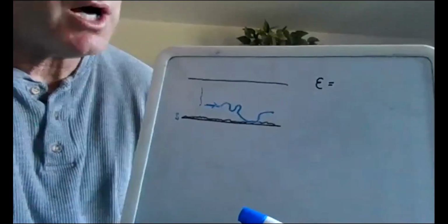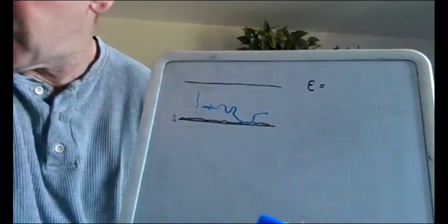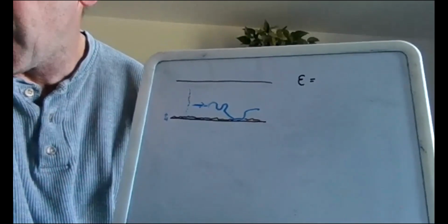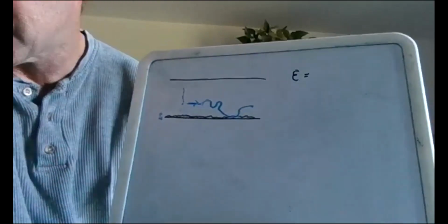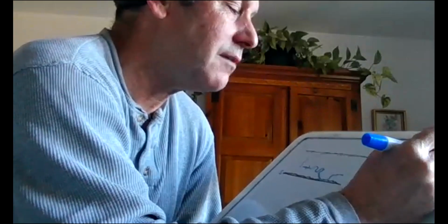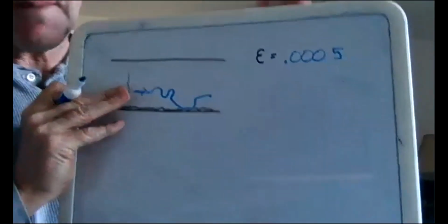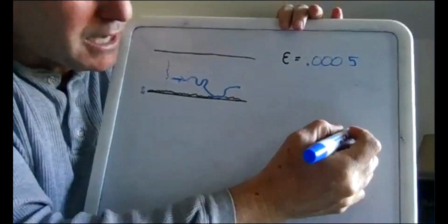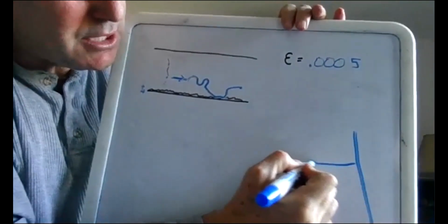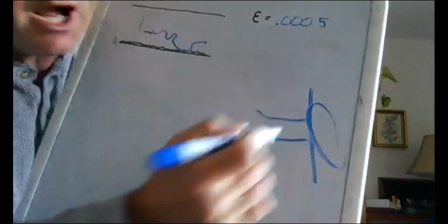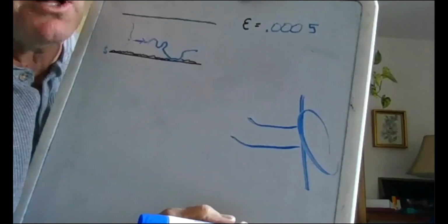All right, so for your Moody chart, table 8.1 in the book nicely has some common pipe roughnesses. We can always look them up for any particular pipe. We're going to do galvanized iron, and so 0.0005. All right, if you think back to the Moody chart, the column on the right side, which we use to get those curves, is not roughness, okay? This is relative roughness.